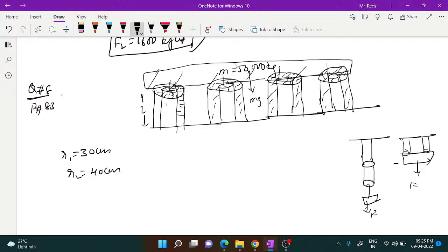What is mentioned here is that all are identical, right? So the force is distributing equally. If this were F1 and F2 with different materials, F1 plus F2 is equal to F, but here all are identical. So you can say the total weight is equally distributed, F by 4, F by 4, F by 4, and so on. What you can understand from this is...